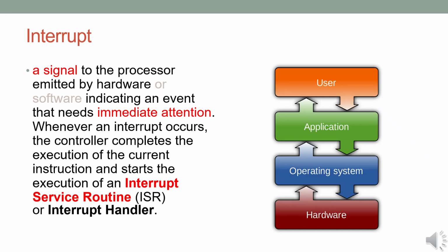Summary: an interrupt allows a program to pause its current task and respond to an event. The event triggers a function called the interrupt service routine, ISR. Once the ISR is complete, the program returns to its original task. This approach is far more efficient than polling, especially for real-time event detection like button presses. On Raspberry Pi, users can implement interrupts easily using Python libraries without needing to manage hardware directly. This abstraction enables developers to write cleaner, more efficient code while fully utilizing the hardware's capabilities.